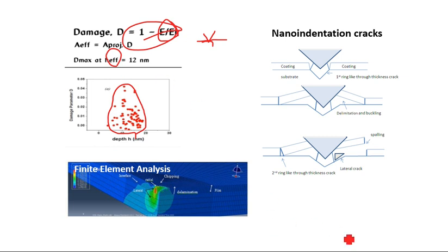Now, an increased value of depth, an increased value of load, at certain times causes cracks or causes a brittle failure or fracture. The geometry of a Berkovich indenter is different from a Vickers indenter for that matter. So even if we are seeing some sort of cracks, the stress distribution is totally different. In the case of Berkovich indentation, this is how the cracking takes place.